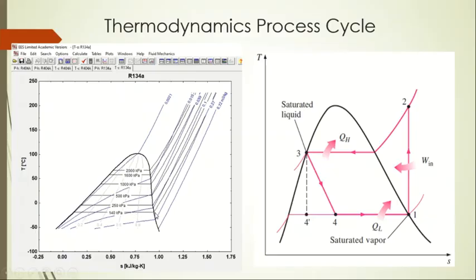The compressor will increase the pressure from 140 kilopascal to 2000 kilopascal, or maybe 1600 kilopascal. Then you have to follow a similar pattern in order to know the actual values of the Q and the W, when you can easily read out this complete table and graph.